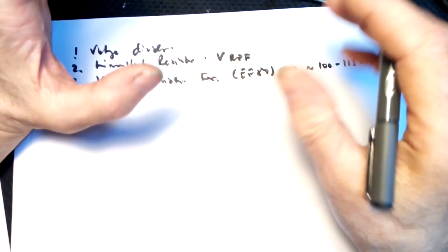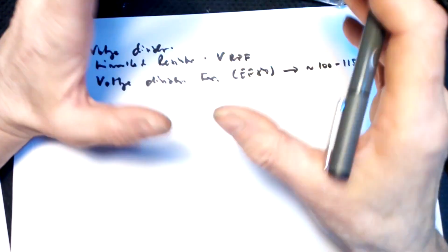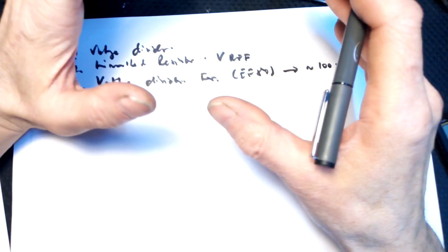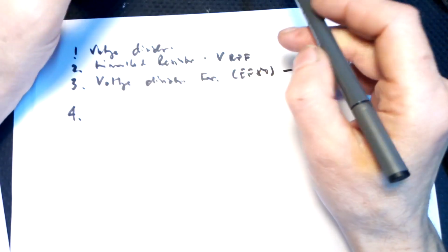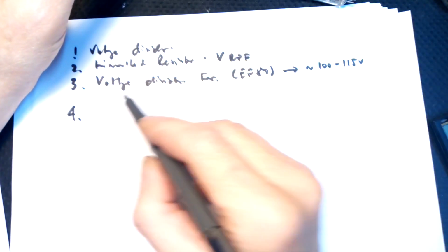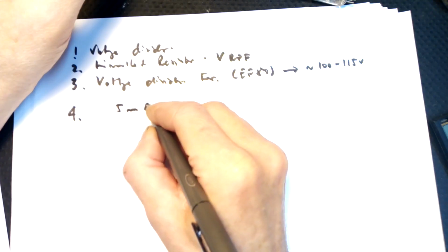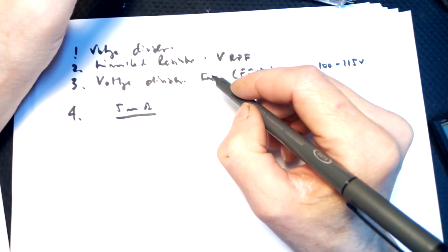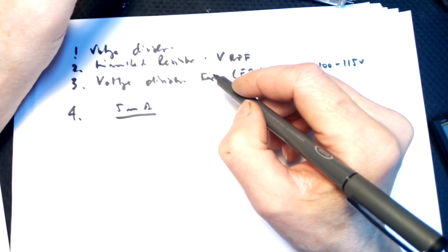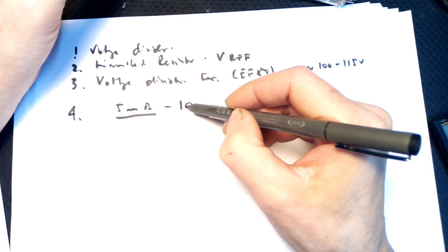We have to remember that this stabilizer needs some load almost all the time to work properly, from switching on. So I think the minimum is at least 5 milliamps of current flowing all the time, maybe 10.